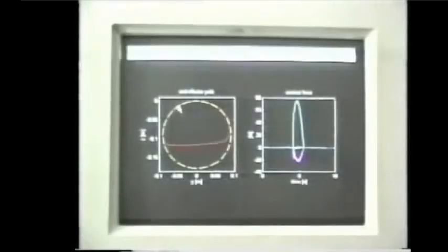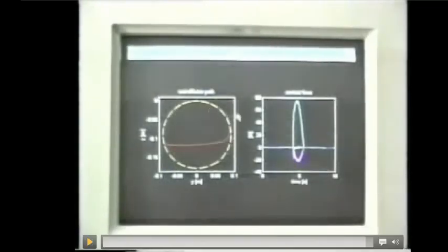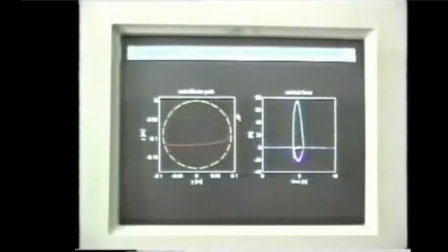And for instance, here you see, let me stop this. In this VCR view, you can see the circular path. So the end effector is tracing the path in the free space. When it touches the box, which is rather compliant, it's a carton box, it will comply with the surface and not move on the tangent of the surface itself, so making an error in terms of position.